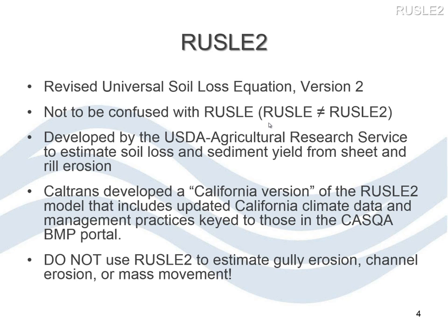In simple terms, sediment yield differs from soil loss and erosion in that it accounts for deposition on the landscape. It looks at erosion, but it also looks at the deposition of sediment on the construction site. And that ends up being the standard that the Water Board holds you to, really the sediment yield coming off the site. The sediment yield in the post-construction condition has to be equal or less than what happens in the pre-construction condition.